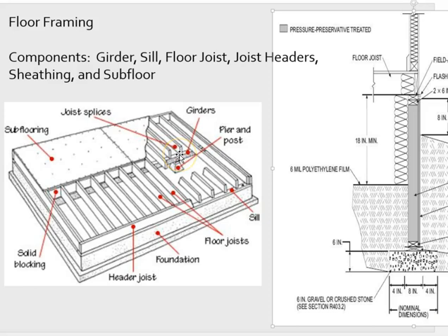That's one scenario. Another scenario is where the joists are ledged flush with the top. The top of the joist is flush with the top of the girder. That's a second common scenario as well, and we'll see that variation. And then the sheathing is being put in.